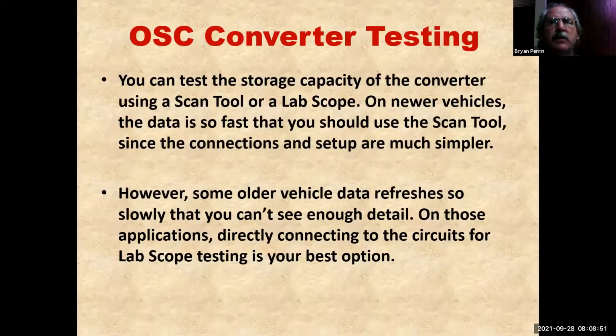So the process I went through on diagnosing a misfire is the same process I go through if the car didn't run at all. Do I have spark? Do I have fuel? Do I have compression? So the process is the same. And if everything looks good the first time, then I go to the next level tests that are harder and take more time to figure out where the problem is. So that is where we talk about this layering of diagnostics.